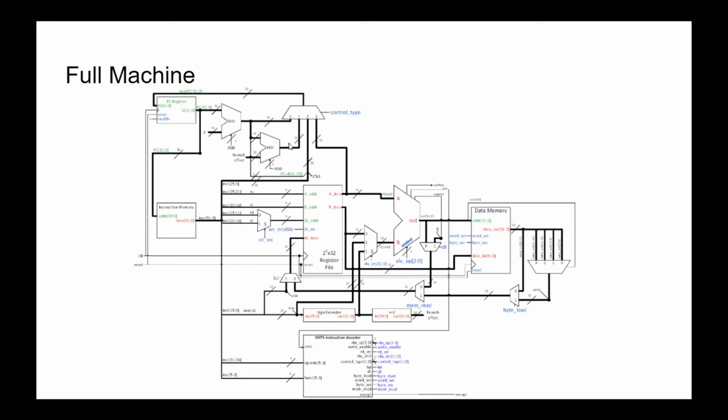And note that I said that this is how you calculate the address for a taken branch, right? Branches are conditional. So for example, one of the branch instructions is BEQ, branch if equal, and it takes 2 registers as arguments. If the values in those 2 registers are not equal, the branch won't be taken and we should fall through to the next instruction. So somehow our control logic is going to have to check whether or not we should take the branch and change which one of these 2 lines it selects between from the multiplexer.